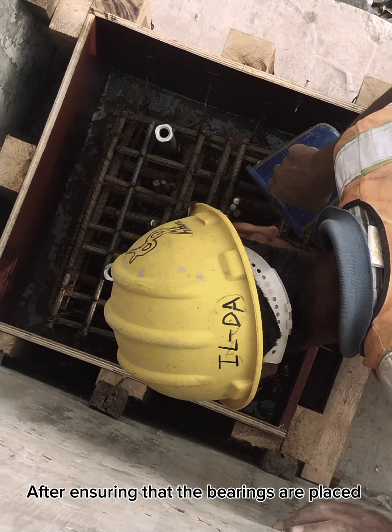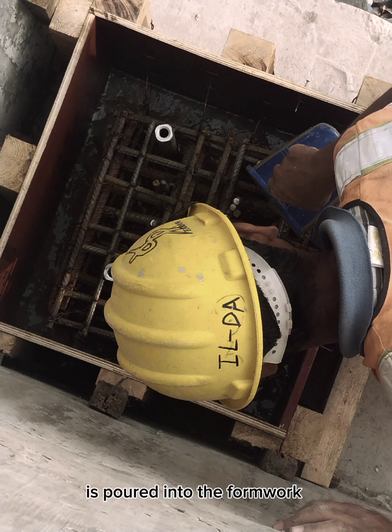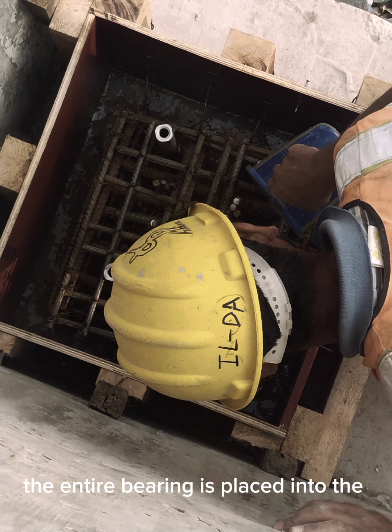After ensuring that the bearings are placed with accurate measurements, preparation of formwork is done. Concrete grade of M40 is poured into the formwork to form the pedestal of dimension 450 millimeters by 450 millimeters. When pouring the concrete, only the anchor sleeves and not the entire bearing is placed into the reinforcement cage.